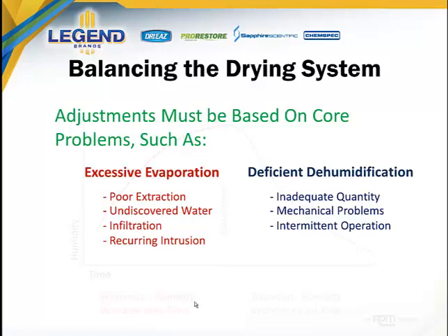It may sound a bit silly, but it's quite truthful that if this is the issue, then the only proper remedy is educating the customer, or the occupant, to try to eliminate the intermittent operation of the dehumidifier. In some cases, however, the intermittent operation has nothing to do directly with the occupants, and it may be just the power system within the building. You may have utilized the power in such a way that the power is throwing breakers, or the power in the structure itself is too old and no longer to spec and not reliable. In these cases, most dehumidifiers of a newer type are going to give you information to help you understand that the power failure has been occurring.